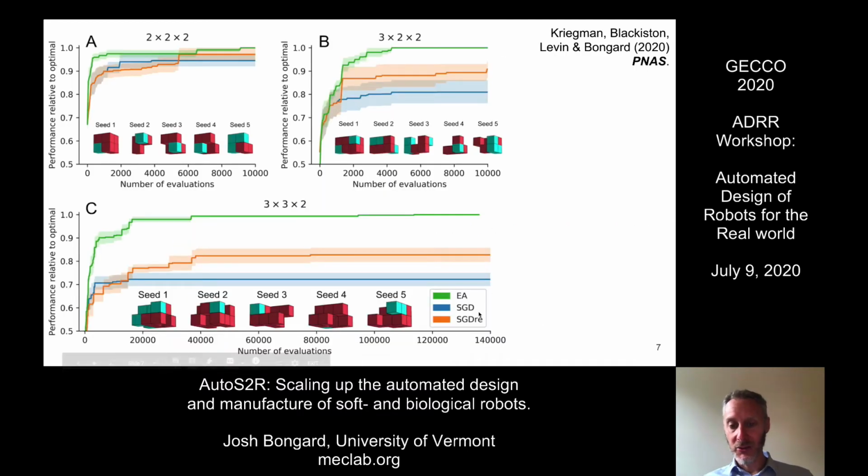The other reason is that stochastic gradient descent typically performs well for fixed-length problem formulations where the parameters are real values. In the case of topology optimization, we have more or less integer parameters. So a 0 can indicate no voxel is present, 1 can indicate a passive voxel is present, and a value of 2 indicates that an active voxel is present. That doesn't mean that there aren't adaptations to stochastic gradient descent that could be made to apply gradient descent in this problem space. But basically an evolutionary algorithm is the way to go for the moment.